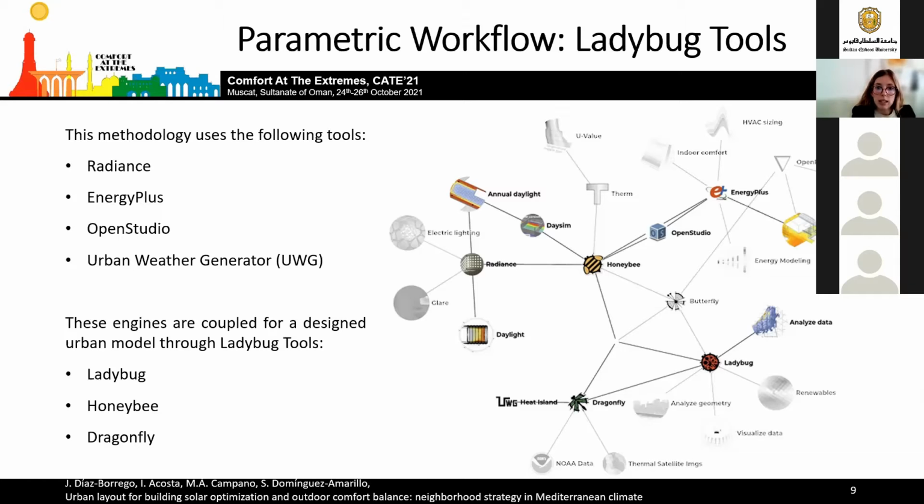In this way, daylight evaluation was carried out using the Ladybug Tools plugin Honeybee. Honeybee allows the evaluation of indoor daylight by connecting the Grasshopper visual programming environment with validated lighting simulation engines for ray tracing, Radiance and Daysim. For its part, Ladybug imports the EnergyPlus weather file, EPW, into Grasshopper.